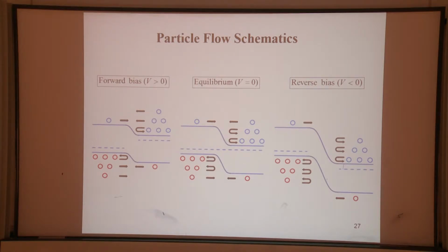So when we put the p-n junction together, immediately when they are put in contact, there will be a transient current occurring, maybe in like a millionth of a second. Then it stops. The depletion width has fully developed, and they become stable and in equilibrium. So this is the equilibrium condition.